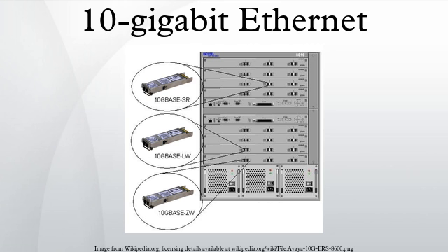SFP+ modules can further be grouped into two types of host interfaces, linear or limiting. Limiting modules are preferred except when using old fiber infrastructure, which requires the use of the linear interface provided by 10GBASE-LRM modules.